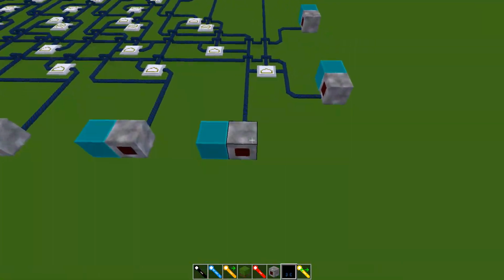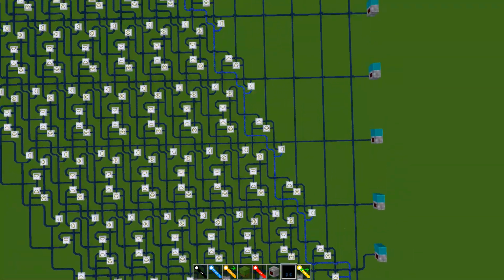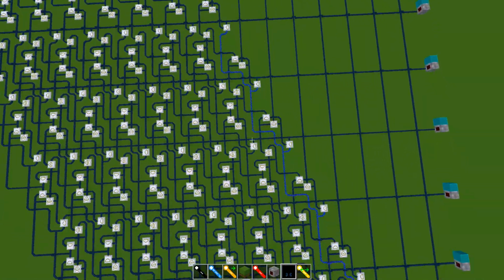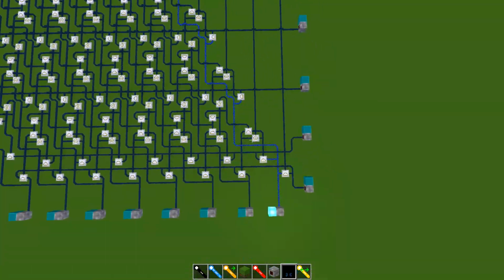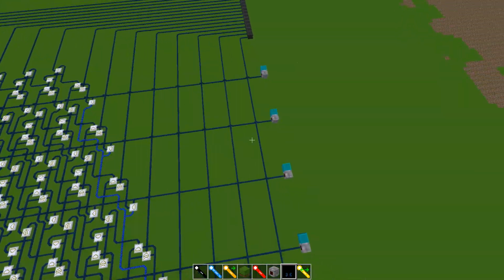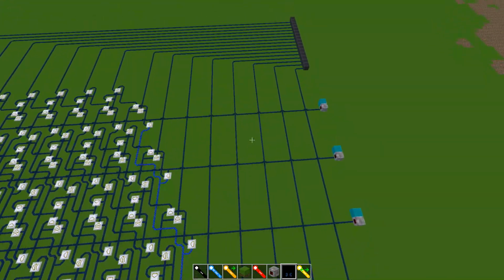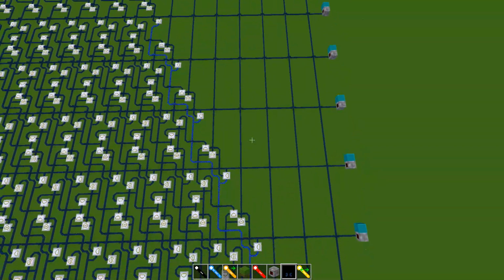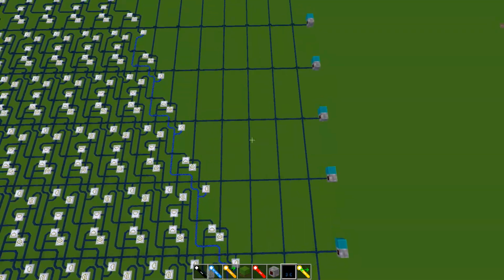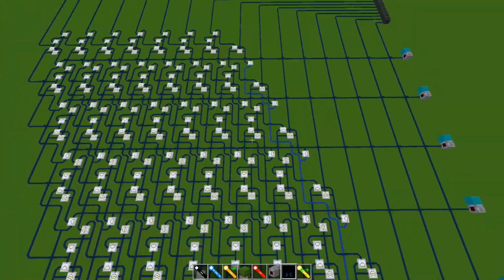So I will turn on the first bit here to demonstrate the effect. As you can see here, the bit is always bit shifted to the left. And then you can see that these outputs here that are already finished, they are no longer dealing with the rest of the circuit. That is because the lowest bits are of course not influenced by multiplying with the higher bits. Right, so that is of course the correct behavior.